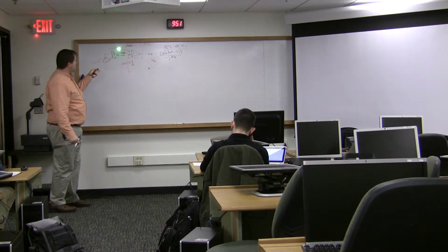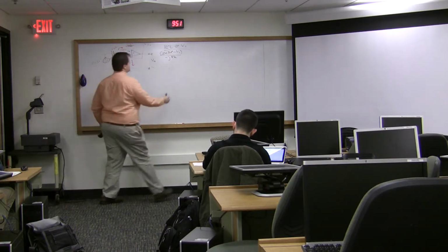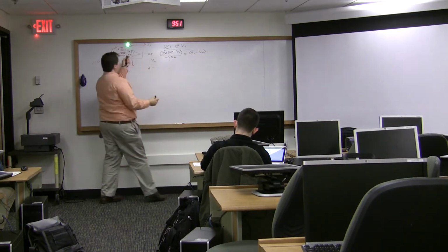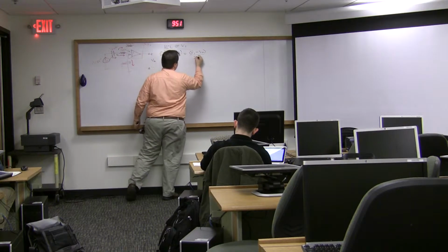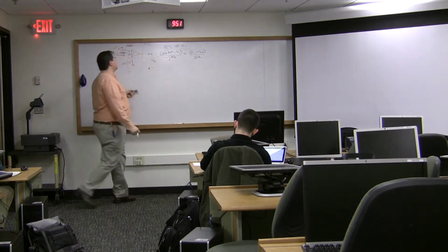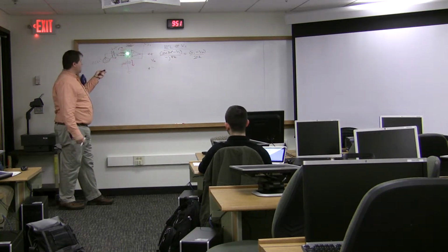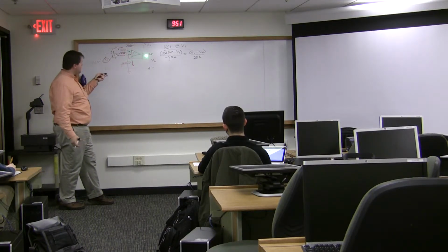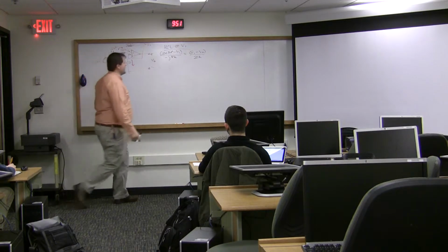Equal currents out, so that's V1 to V0 divided by the 20 kilo ohm resistor. And then our final current out is V1 to V0, because we do know that that is V0, even though it's a different point in our circuit, divided by 10K.